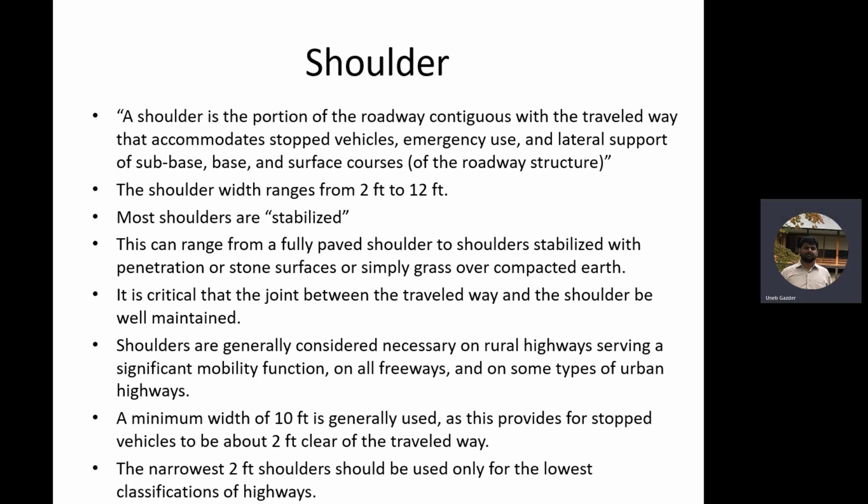You can't stop anyone. Sorry? In local roads, you can't stop anyone. Yeah. So if the road is low speed and low volume, even a car which is half on the lane, half on the shoulder is not a big issue. So you try to save your space by providing a smaller shoulder, because the risk is lower. Even if a car is stopped on the shoulder in emergency and it is somewhat on the lane as well, it's not so dangerous.